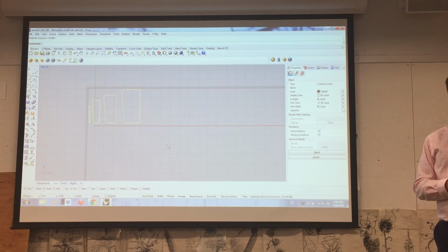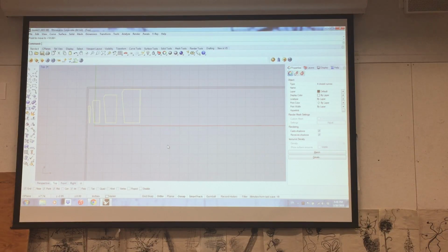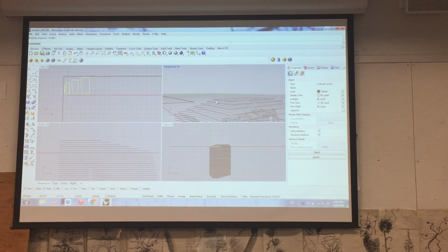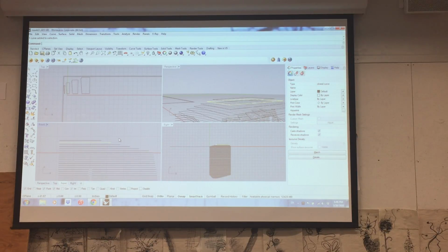You were saying something about layers, like in the middle, and I don't understand what you mean. Well, what I meant is in the process of moving all of these layers to exist on your chipboard sheet, I wouldn't select them in the perspective view in this method. I would do it just layer by layer, in a perpendicular plane.